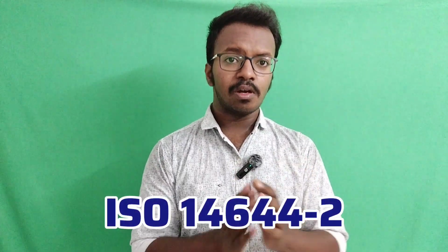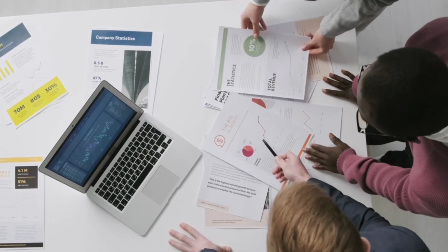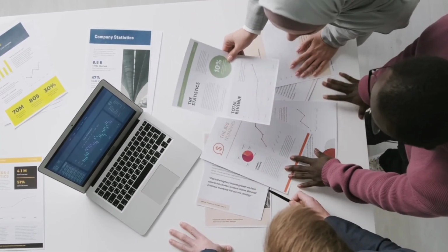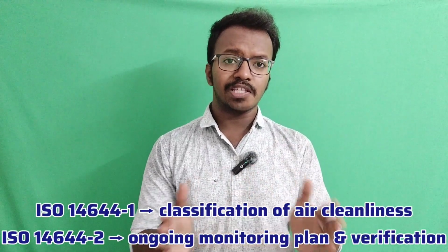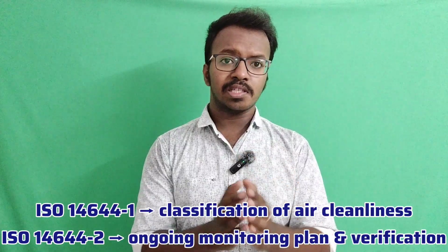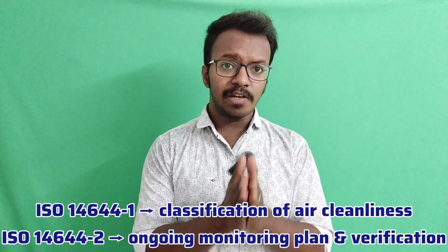Please watch it. The next one, ISO 14644 Part 2. This part 2 is used to prepare a clean room monitoring strategy and maintain the clean room parameters as per Part 1. What is the difference between Part 1 and Part 2? ISO 14644 Part 1 describes the clean room classification. Part 2 describes the monitoring strategy, ongoing monitoring plan and verification.